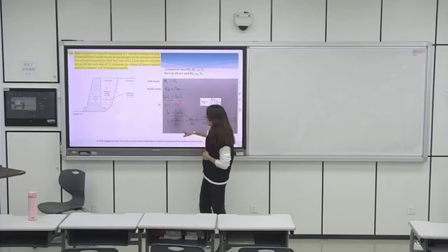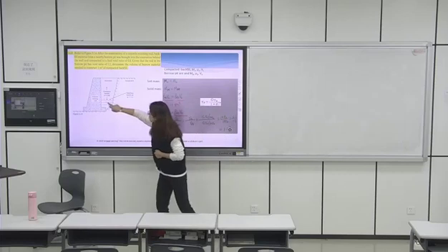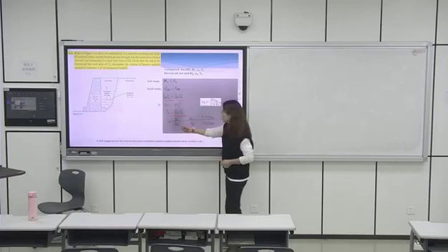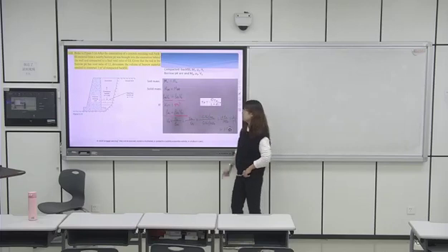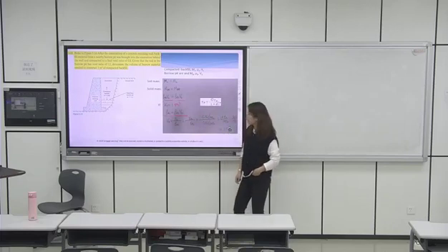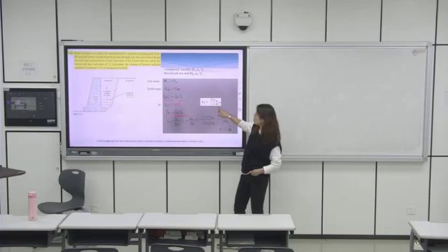Then VB, how much is VB? VB actually equals the density from this side divided by this side. Got this. And the ratio of density equals the ratio of unit weight. Because unit weight can be calculated with this equation, we know the void ratio, then we can get the results, right?